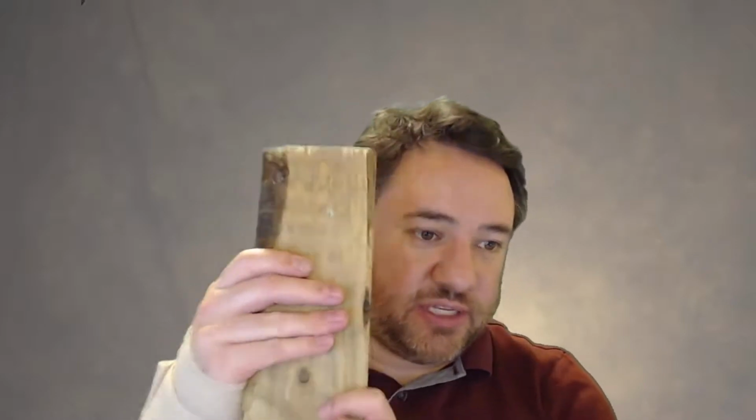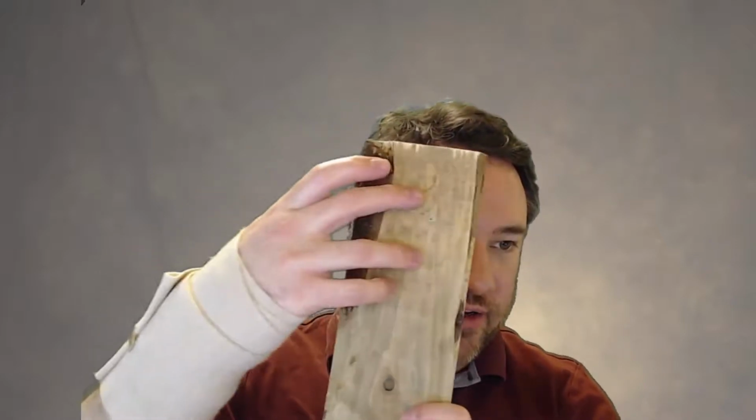So for this member, I'm not calculating splitting at all. For this side of the connection, I'm going to calculate row shear. I'm going to calculate net tension, right? So for 2 sides of the connection, they could be 2 different materials, and they could also be in 2 different directions, which means that I'm going to use different calculation methods to calculate the strength of each.